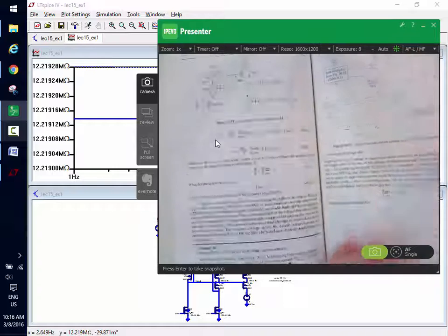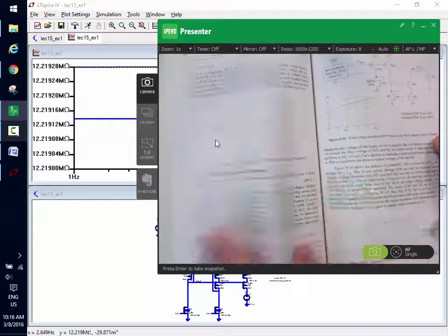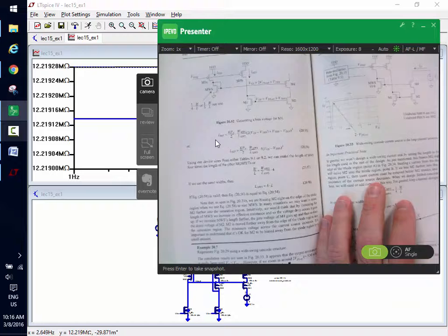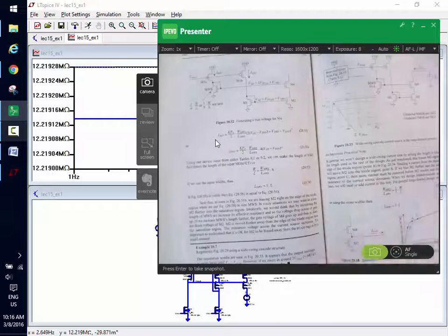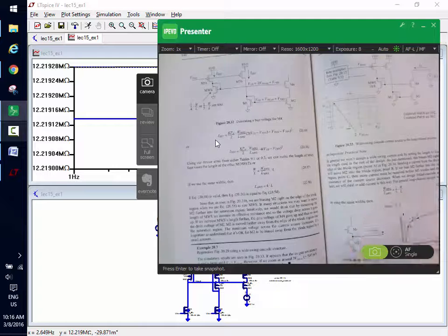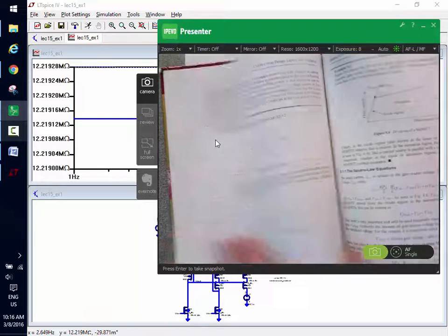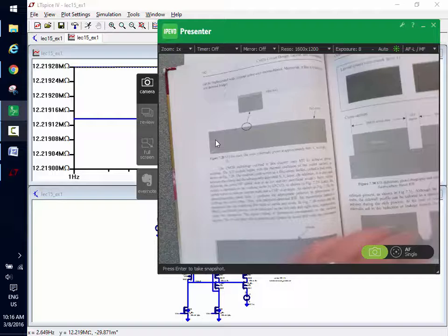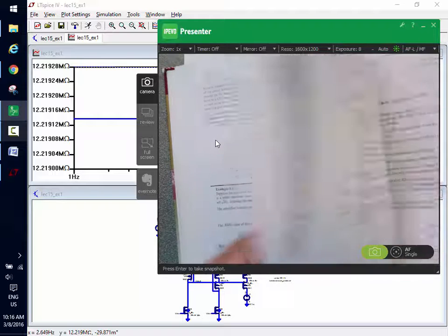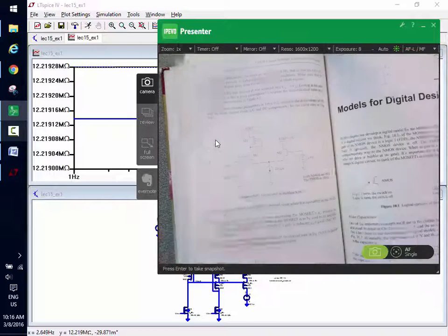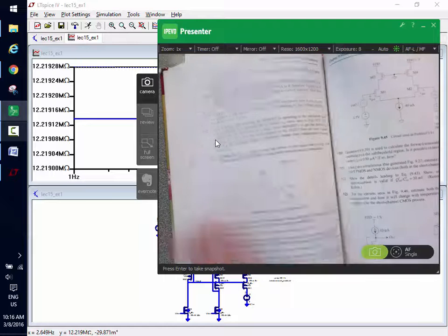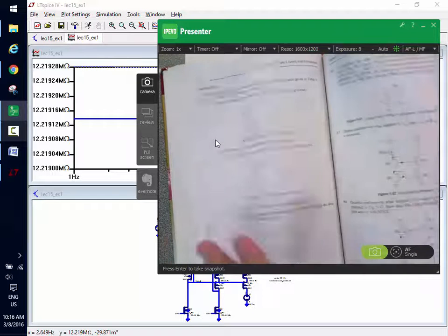It's going to vary because of lambda. I'm changing the drain to source voltage across this top device here. Yeah, remember in chapter 9, one of the big deals we did was we said, hey, when we get output resistance, it's not going to be precise for the nanometer device, because look at this plot. And we went over that.